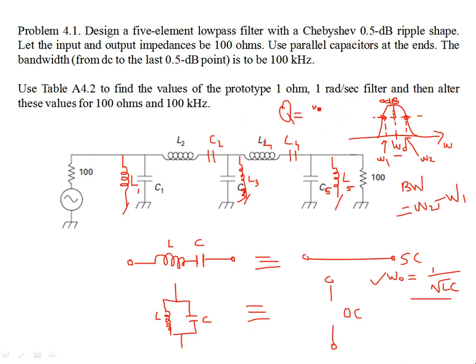It's the center frequency divided by the bandwidth, and it determines how selective your bandpass response is. For example, if the bandwidth is very narrow, then it's going to allow a very selected range of frequencies strictly, not allowing any stray frequencies to pass through. So for a very narrow-band filter, we are going to have a high Q bandpass response. Okay, so this is another factor which measures the sharpness of the response, let's say.